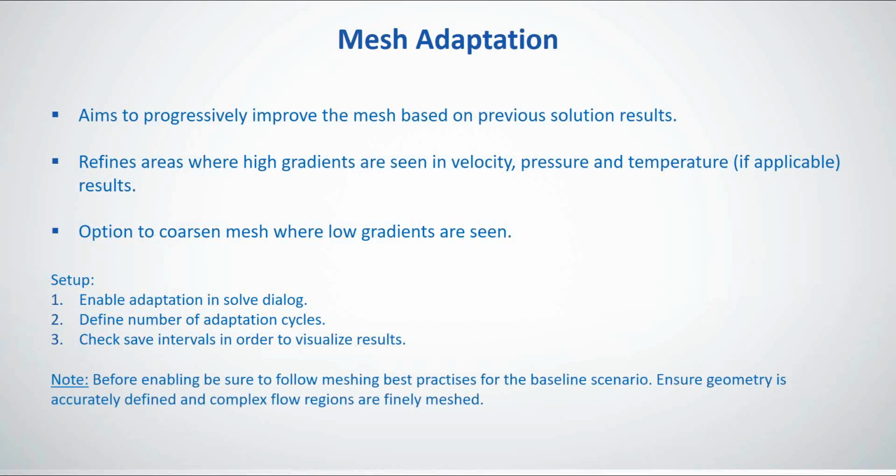Yep, it is always better to apply meshing best practices before you apply the adaptation, rather than just going with the automated mesh, because it's an automated process and you're probably better with a bit of manual refinement in the areas of interest.